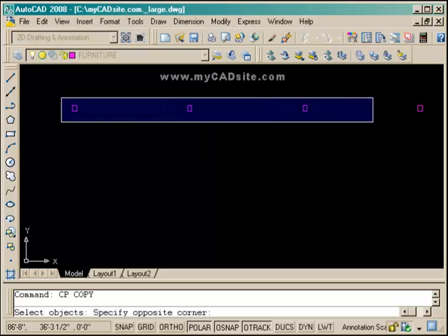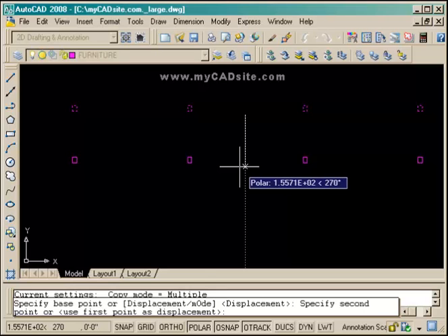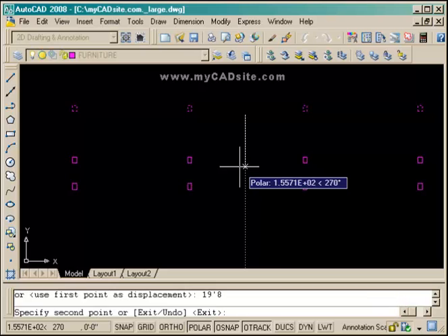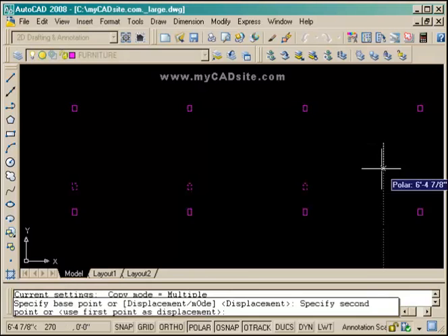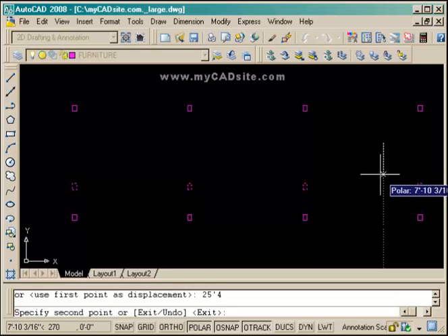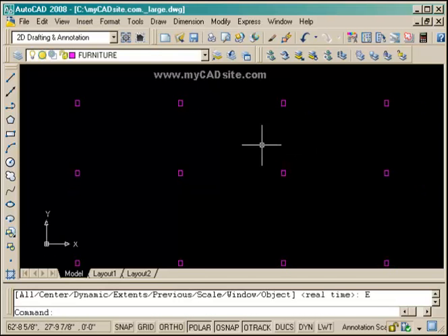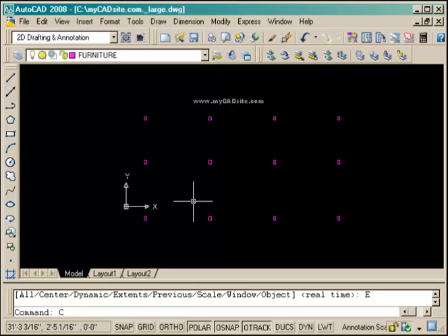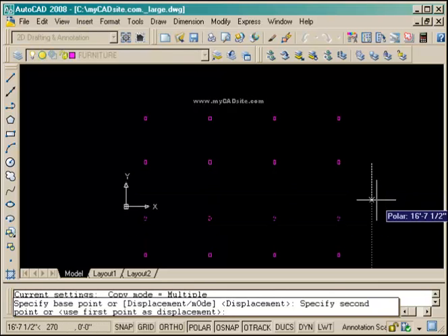Now what I want to do is copy the blocks down, and using the measurements, I'm using the copy command to copy all 4 of them straight down. I know that not all of them are used. Some of them are, some of them aren't. But they are in a grid pattern, like most columns would be. So I'm just going to copy them down. Now I have one more row at the bottom, and copy those down.